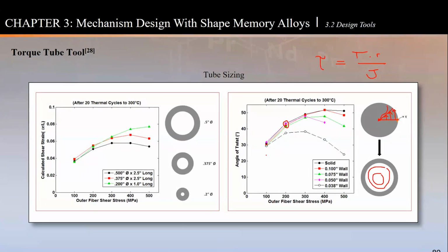Yes, so we cut the tubes, we gun drill them, we spline them or hex them on the edge, and then we don't shape set them, but we train them. Okay, so that's the only two ways to get the form, by shape setting and jigs, or by training them to remember that shape. And the training is apply a twist to it and do a bunch of other things. Suddenly the tube doesn't know to extend or to bend and only knows how to twist. So that's what that training does to it, really.